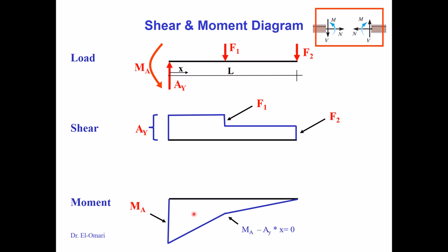This indicates that you will also see, when you continue with mechanics of materials, where is tension and where is compression in the beam. So this also indicates that there is tension on the top and compression in the bottom of this part. Important locations would be where the maximum moment is, where there's a change in the moment, maximum shear, a change in the shear, and also at the support. It also helps us design the supports when you move on with the design.